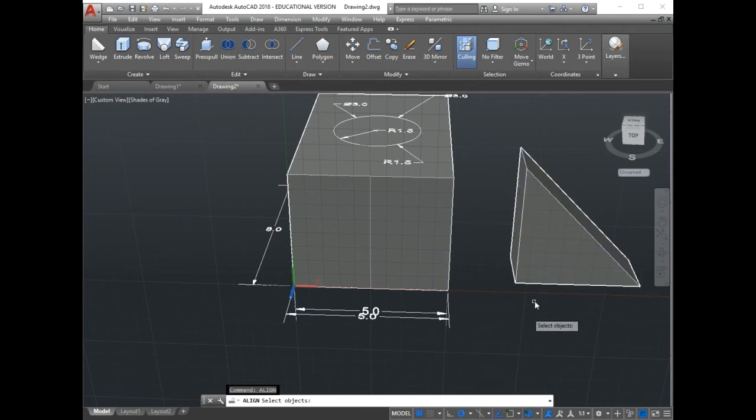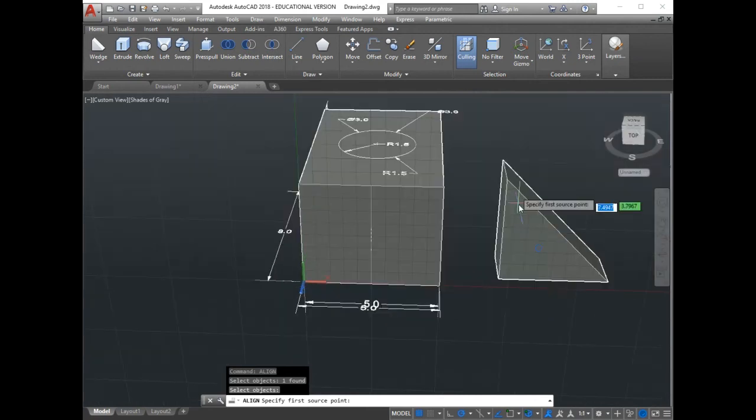Okay, now guys, select the object. Remember, for the alignment, usually we pick up the object that will be moved, not the one we will move it to. So you choose that one and then right click and be ready to define your source and sinks. Remember I told you that your first point is the most important one. So what we need to do is to pick up the mid of that edge to be my first source.